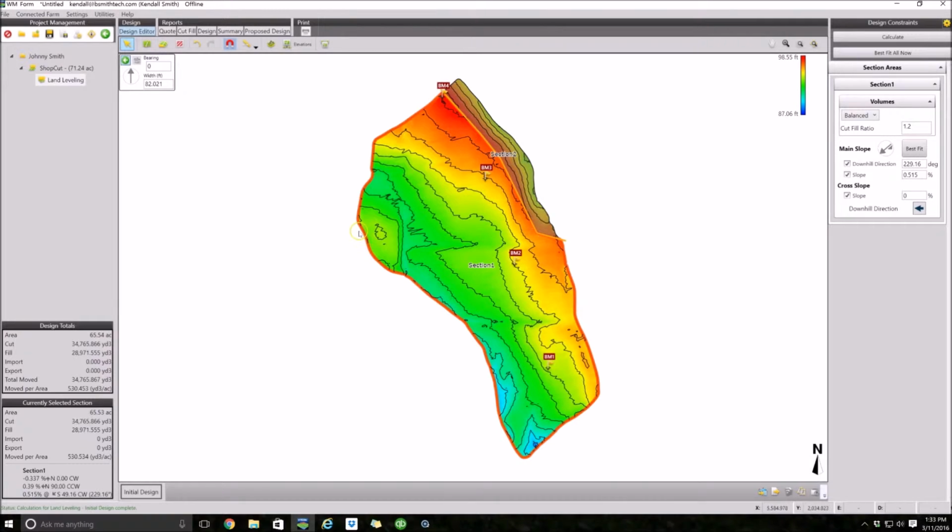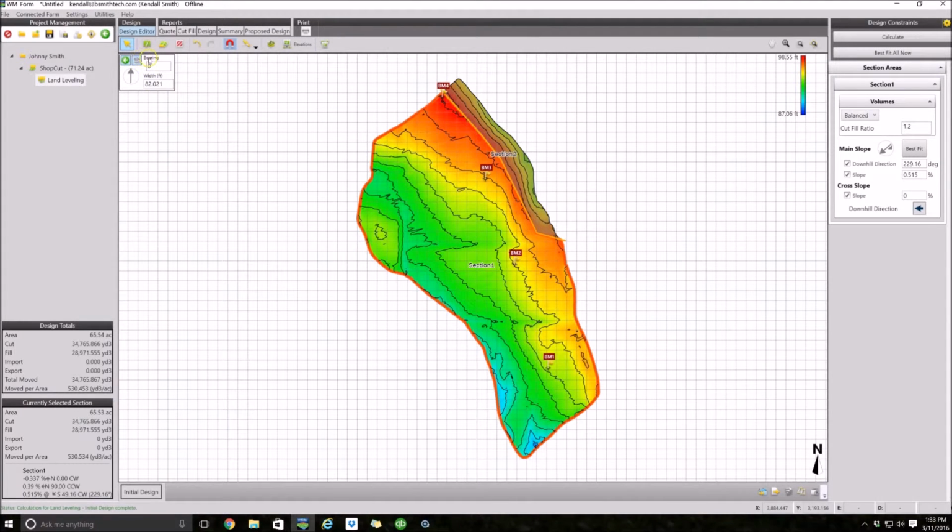Now, I would like to show you some cool little features here in the background. One of them would be a grid size in the background of the field. We can change the bearing of that grid. So we would like to match this north side as close as possible, so we can get that coordinate by just using our measure tool. Going from one side to the other, we're looking at 233 degrees there where it's got that B in the middle of that box, 233 degrees.